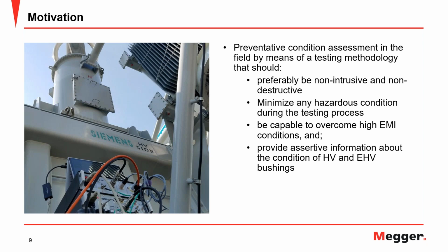So the idea is to keep the insulation system inside the bushing as it came from the manufacturer. So we prefer to have non-intrusive and non-destructive methods to do the analysis. We try to minimize any hazardous conditions during the testing process. And one of the big challenges that we have is, of course, this is a low capacitance object. And if you go to high voltages and extra high voltages, the effect of the electromagnetic induction in the substation, of course, will create some noise that we need to overcome in our testing procedure.